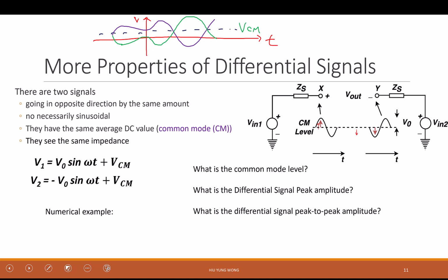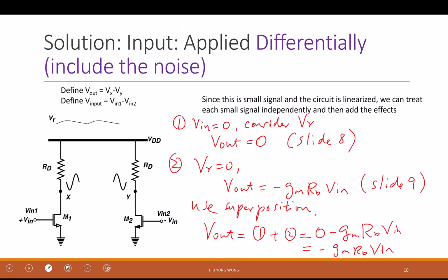It's two signals. You need to physically generate two signals, like here. If you have a microphone, it's just one signal, then you pass it through a buffer or something and flip it, and then it's two. For that one, you can make a center tap on the transformer, and then the center becomes the ground.